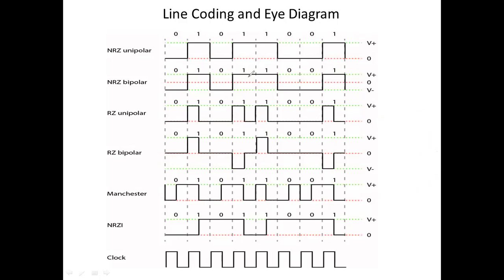So other than this line code, sometimes they suggest you go for a code which looks something like this, a sinc in the time domain. Instead of sending the square boxes, we will go for sinc waves. Which, what they do is they give you a rectangular box in the frequency domain. So when there is a rectangular box in the frequency domain, it will be a very proper utilization of the frequency domain. Efficient frequency bandwidth utilization is going to happen. So that's why an ideal pulse is not this kind of square boxes.